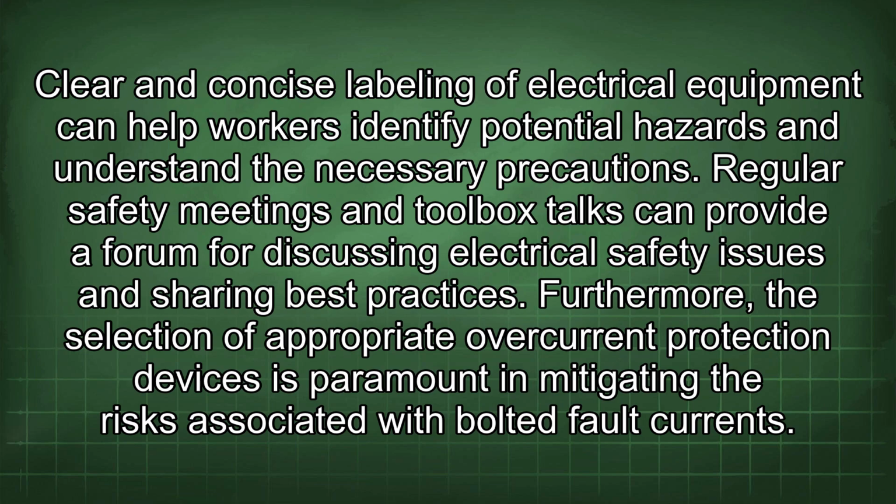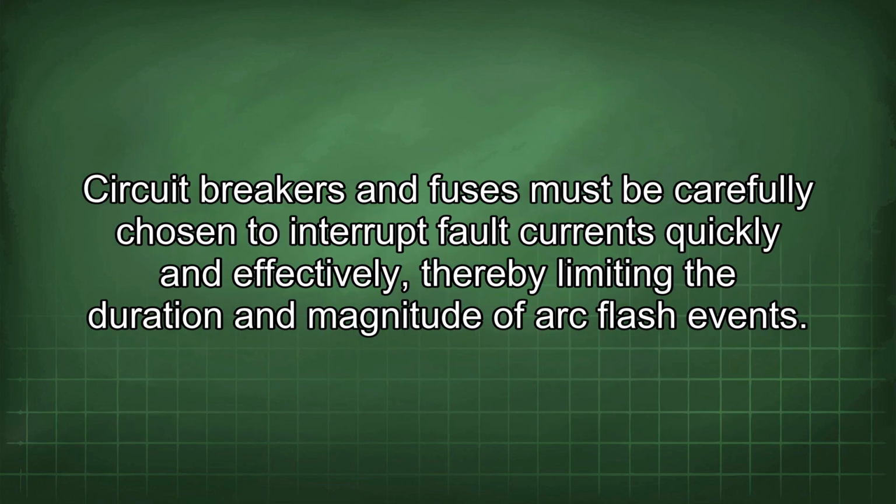Furthermore, the selection of appropriate overcurrent protection devices is paramount in mitigating the risks associated with bolted fault currents. Circuit breakers and fuses must be carefully chosen to interrupt fault currents quickly and effectively, thereby limiting the duration and magnitude of arc flash events.